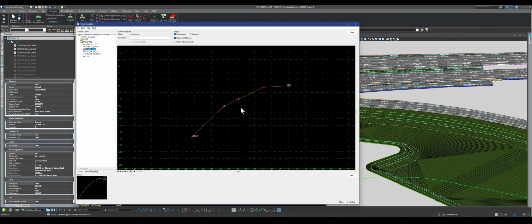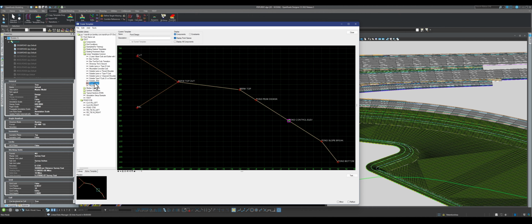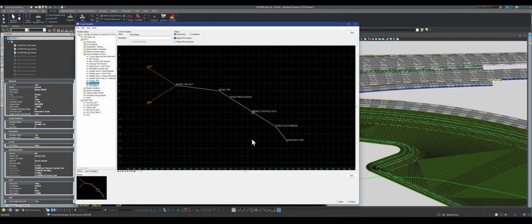And now I want to show you something. And this is for my YouTube people. This is just for the Florida workspace. So remember this resources one. Let's go there. For some reason, FDOT already has a pond template, but I don't like it because, like I said, when you create this, it's up to you. I could have made the center at the bottom instead of here. It's up to you how you want the template to be, right? So let me show you the one that actually comes from FDOT. It's under linear template common. You click on pond, and this is what they have. They actually have the control here in the center.